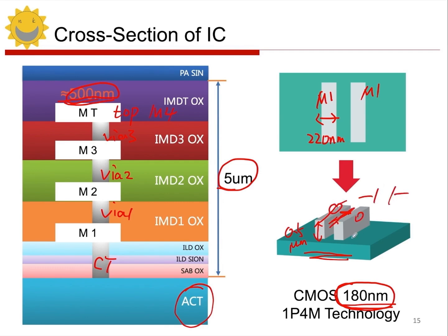The size of the capacitance is related to the area of the metal plates. So you can see that the metal has a certain thickness of 0.5 microns, which is quite thick. If the distance is long, the parasitic capacitance between the two metals cannot be ignored, and it will affect your signal. We will have specific explanations on how to estimate this impact later. For now, just have an intuitive understanding that this parasitic capacitance exists.